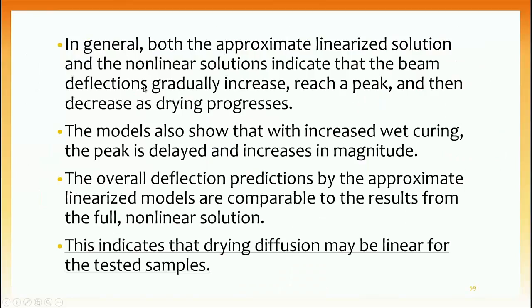So in general, both the approximate linearized solution and the nonlinear solution showed that the deflection gradually increases and reaches a peak of deflection and then decreases as drying continues. And the models also show that with increased wet curing, the peak is also delayed and increases in magnitude. And the overall deflection prediction by the linearized solution is comparable to the results from the full nonlinear solution. This indicates that drying diffusion may be linear for the tested samples.